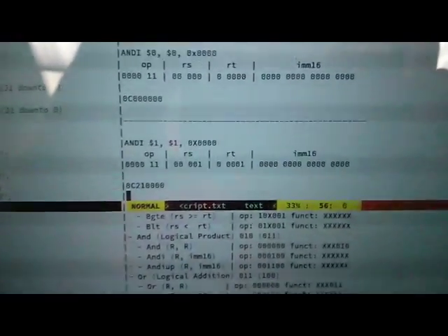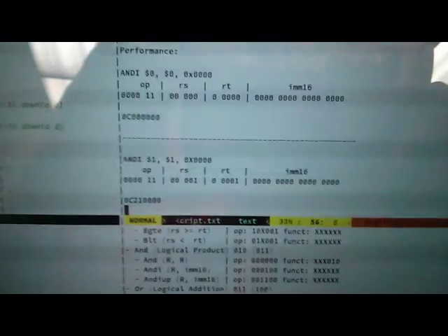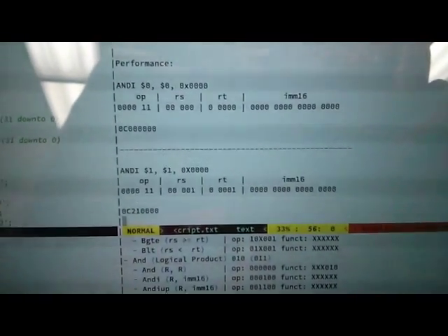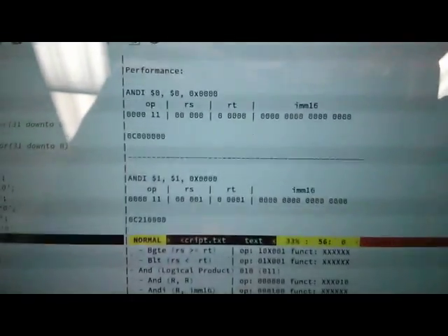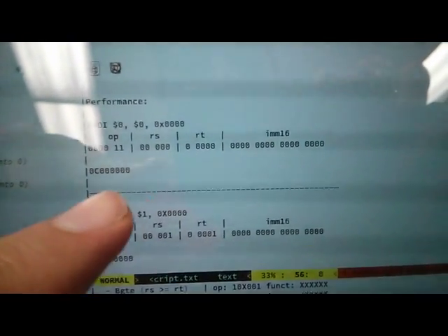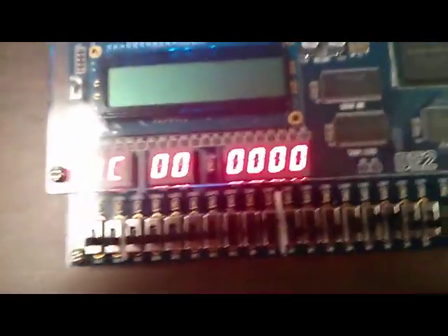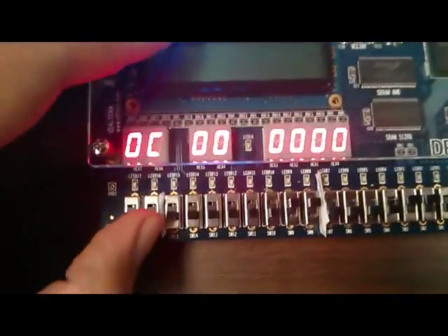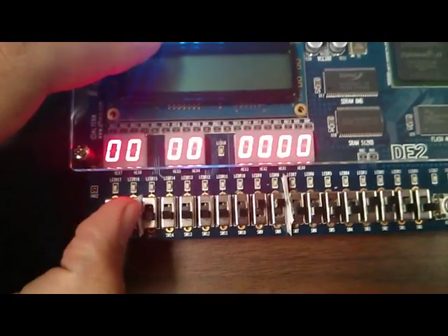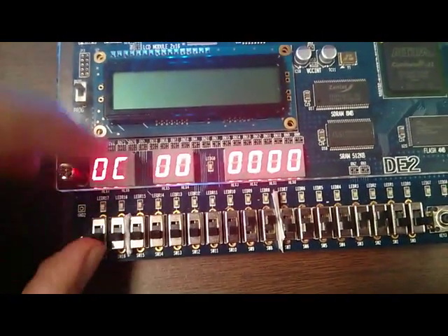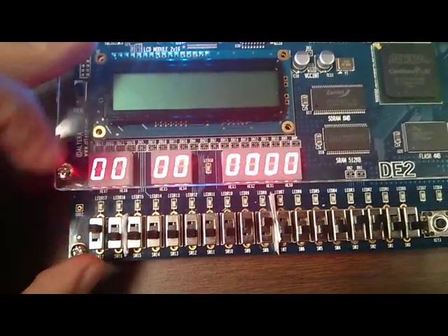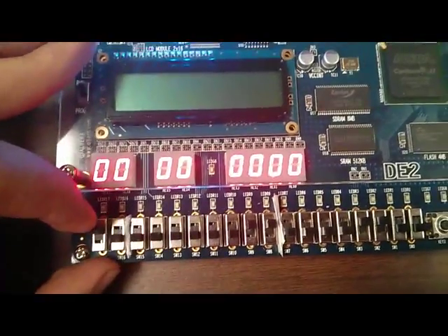So first, we're going to set two registers to 0 so that we can freely add to them, make one 2 and make one 3. So to set register 0 to 0, that's the instruction, which has already been placed on the board for convenience. And when I execute this instruction, my program counter should display 4, and my ALU should display 0, like it currently is.